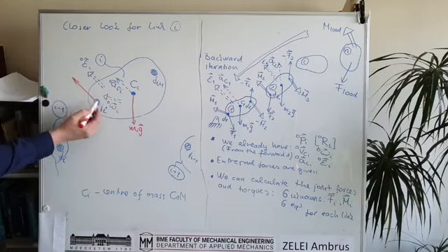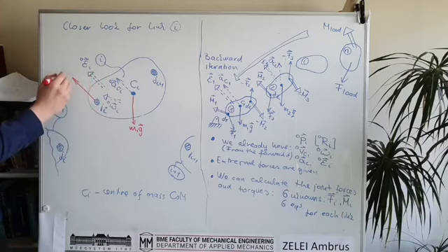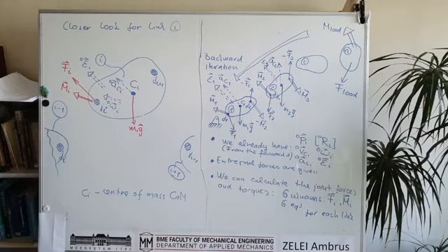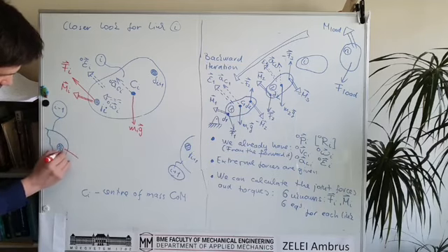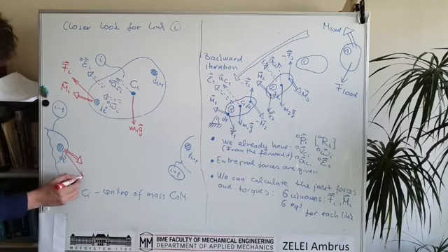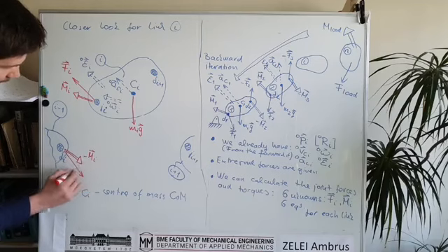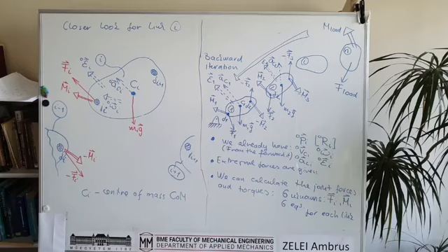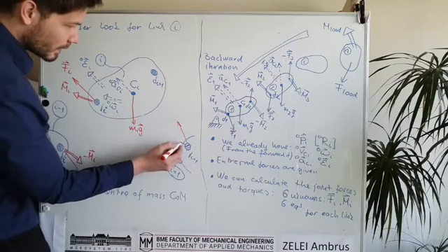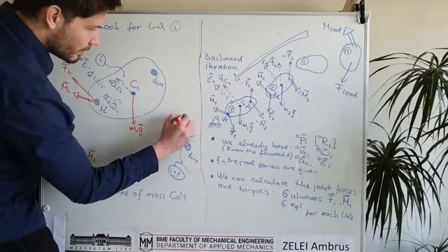So in Ji, in relation to link i, there is the joint force Fi, and there is also the joint torque Mi, and in the previous link there is the same torque and force multiplied with minus 1. So this is minus Mi here and minus Fi, and therefore we also know that in the upcoming link there is Fi plus 1.